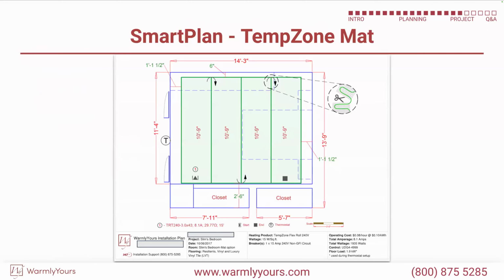Right. So let's talk about this particular plan. This plan is that self-leveling job that we've shown, and the thermostat is over here on the left, and the start is right here. That's a triangle, and that's roll number one. There's only one roll here, but we always number them. And that coincides with the number down here. So it'll tell you what system is used. So we know how many watts per square foot, what size breaker, what the floor is, and what the subfloor is. All of these questions that we're asking you when we're setting the order up.